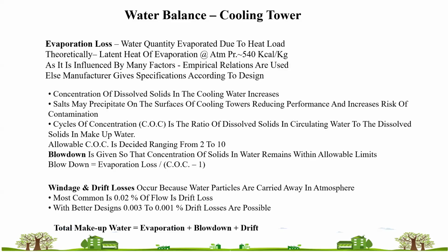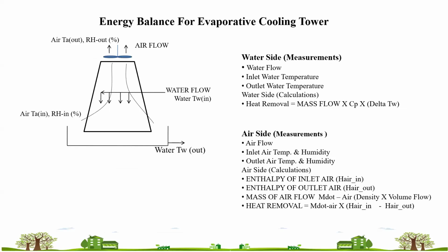So this is the water balance of the cooling tower. Then what is the energy balance? Energy balance means how the typical energy is transmitted in that particular system. On the water side, what happens? You pass hot water inside the cooling tower from the hot nozzles on the top of the cooling tower. Water flows inside that, and there is some temperature of that particular water.